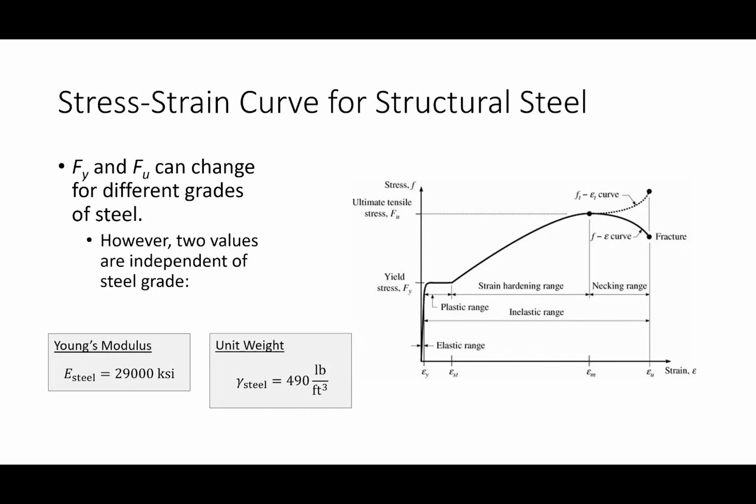You all know that steel, at least for its beginning load application, sort of behaves like a rubber band, that it will behave elastically until you hit yielding. If you keep your stresses below yielding, when you let it go, it snaps back to its original condition. Once you get past yielding, you start getting permanent deformations, right? One analogy that I heard a long time ago that I really like is that one of the advantages of structural steel is that steel is a material that is very ductile.